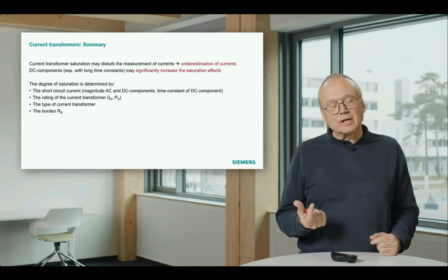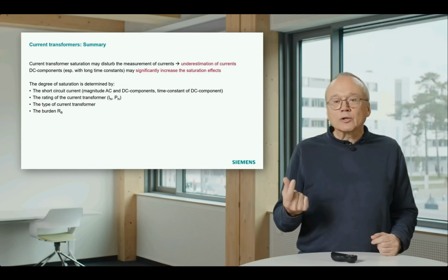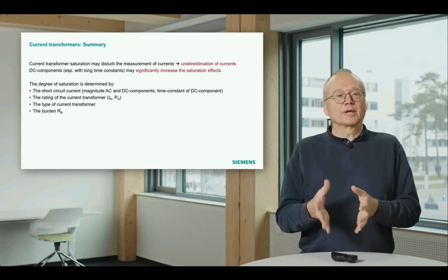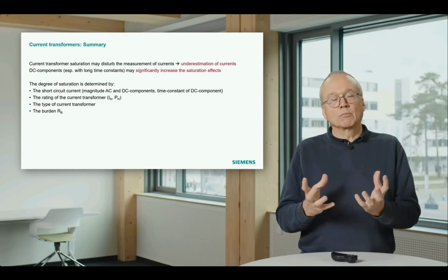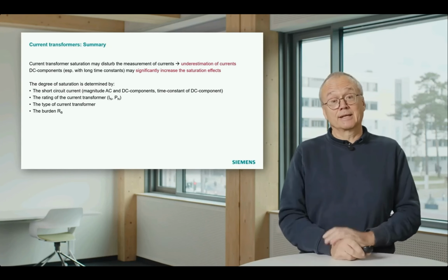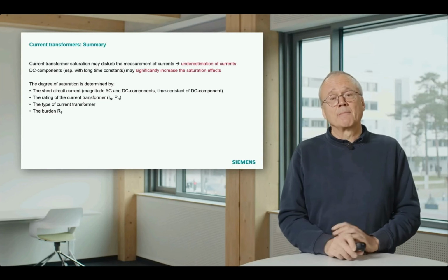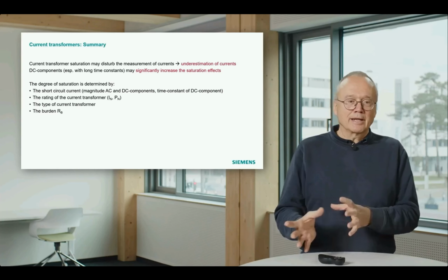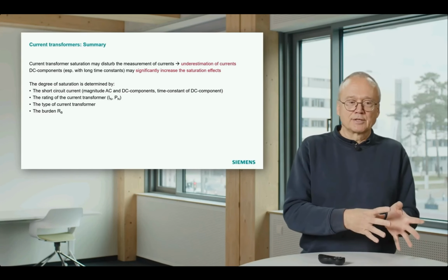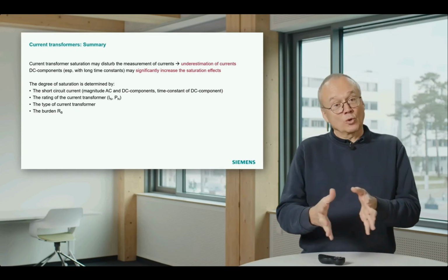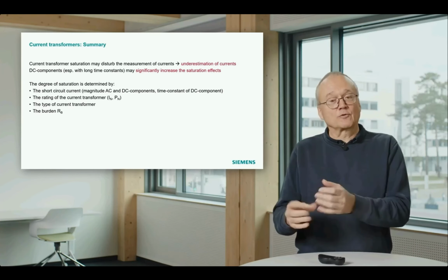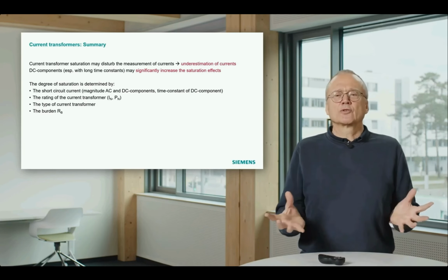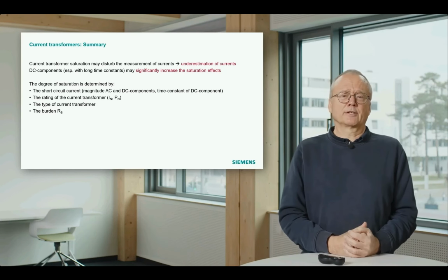And in a protection relay, you have typically not one algorithm, and the manufacturer doesn't want to tell it to you. No, that's not the issue. The issue is normally in a modern protection relay, especially in a distance protection relay, you have some adaptive algorithms. That means you have algorithms who can be fast if possible, or who are slower if they have to be more accurate. So there is not one algorithm.